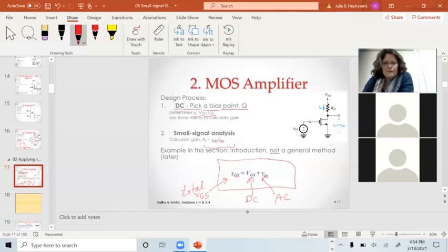That one it's hard to read. Okay, so we got DC and AC. When we're talking about gain, we're talking about the AC gain. What the DC is used for is to set the bias point, to put it at the correct place on that voltage transfer curve.